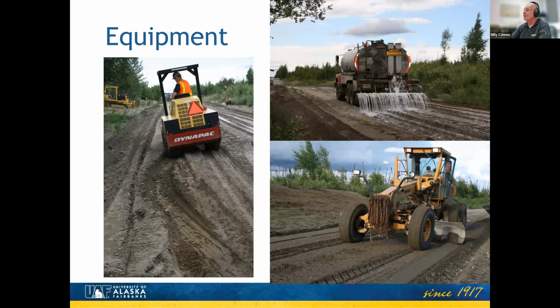The downside is if it gets a pothole, you have to patch it somehow, but the way I patch it is simply take a bucket and mix some of this in there and pour it out into the hole, tap it down, and walk away. And it works pretty well. But once it gets too far gone, you're going to have to grade it, and then you get to start over.